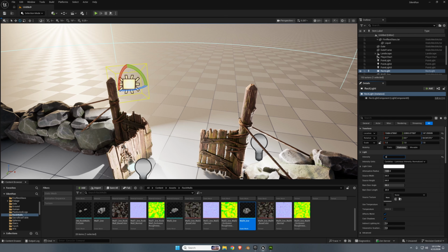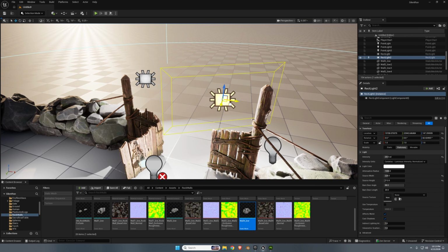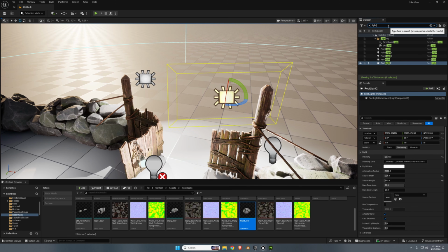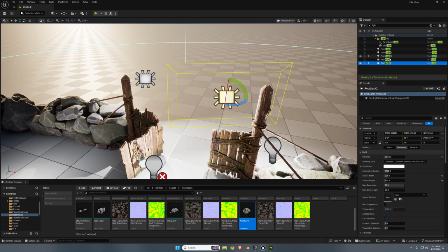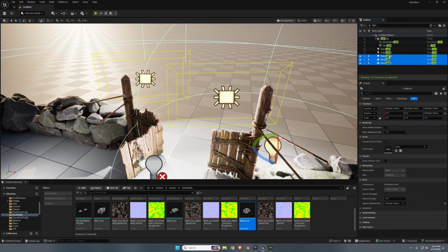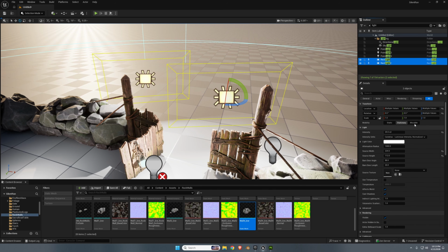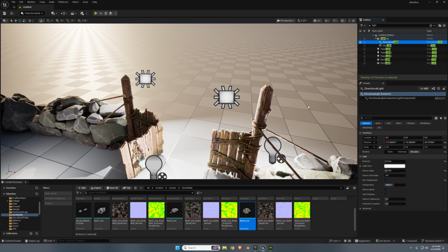People often forget the rim light. You want to place a light behind your object so that it creates these highlights on just the edges of the gate that you can see here. This will make it also pop out a little bit more from the background, especially when it gets a darker background once we dim the lights here. I'm just gonna see how this little X thingy here is. This disappears once you set the lights to be movable. So there we go, that's done.